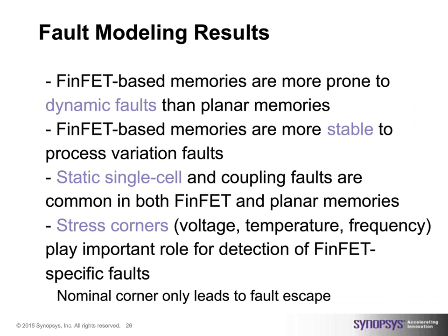Which means that if we need to maintain the proper quality of our chip, we need to have multiplicity of voltage, temperature, and frequency points under which specific segments of the algorithm need to be run. And we have done all that homework, so we know exactly under what voltage, what temperature, and frequency the changes need to happen. And test escapes will not be possible in that case, given what we have seen.